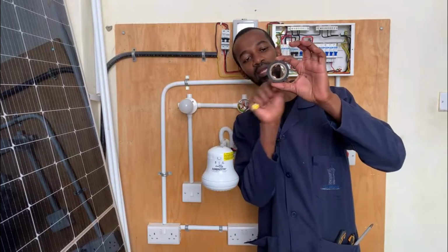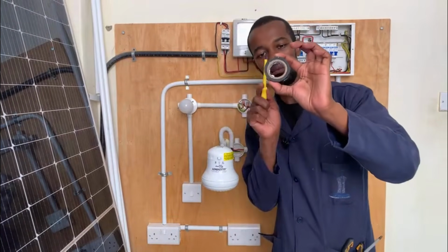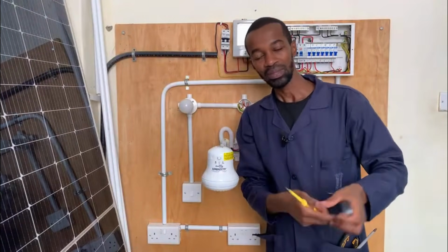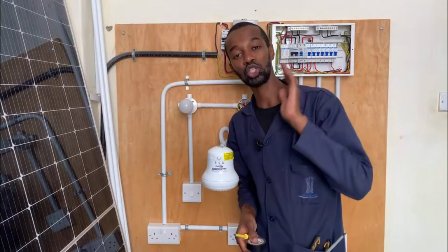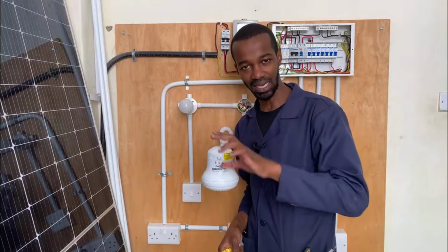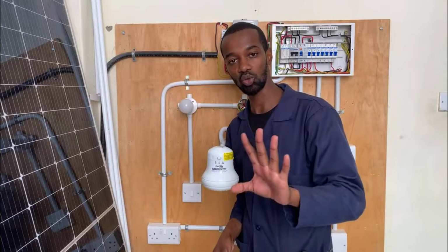So everything that you place inside of that loop is very, very intentional. An MCB to a specific circuit, let's say it is a lighting circuit, is placed there specifically to shut off the supply of current in that circuit if there is an issue on it.